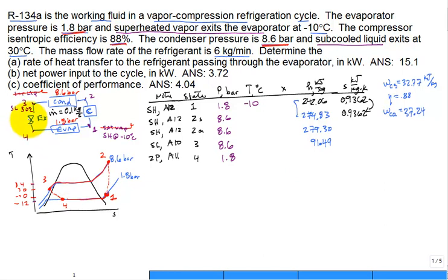All right, how about going through that expansion valve? Well, we've done that a number of times. You do a control volume around it, steady state, no heat, no work, no change in kinetic, no change in potential energy. It's isenthalpic. It's 91.49 kilojoules per kilogram.